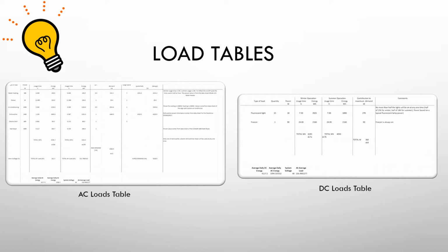The power ratings were found by searching for a suitable appliance for this household that fits under the necessary load bracket. For example, the hairdryer is only on for about 5 to 10 minutes each day, so it seems likely that only 2 people live in this property. And since only 2 people live there, it seems logical to have a drawer-style dishwasher, as opposed to a full-size dishwasher. By making this decision, the power rating of the dishwasher is lower than it would have been otherwise. Similar logic was applied to all different types of loads.